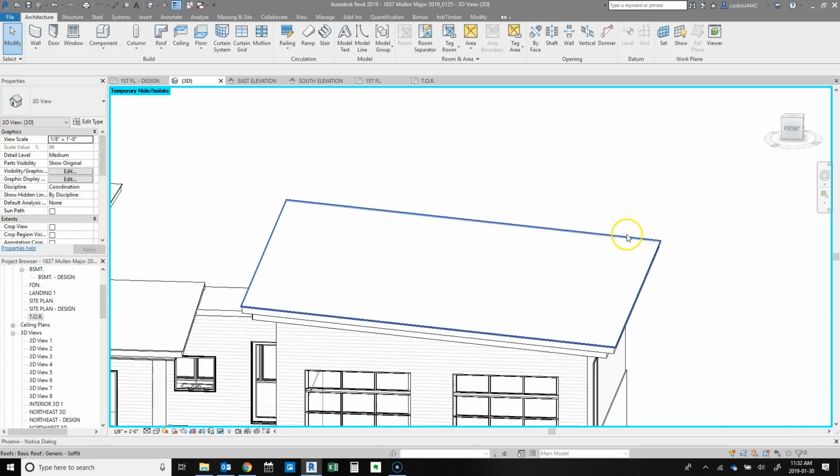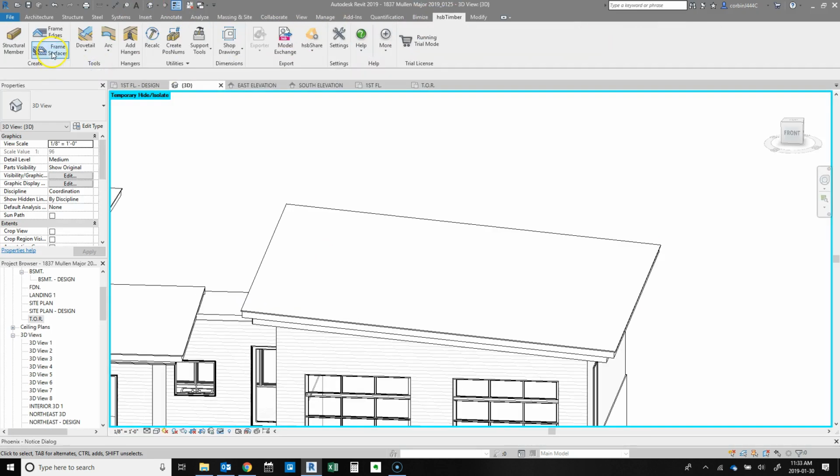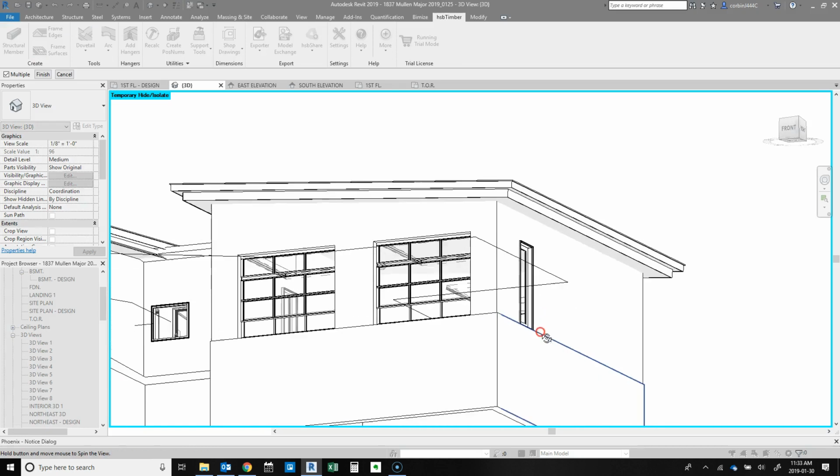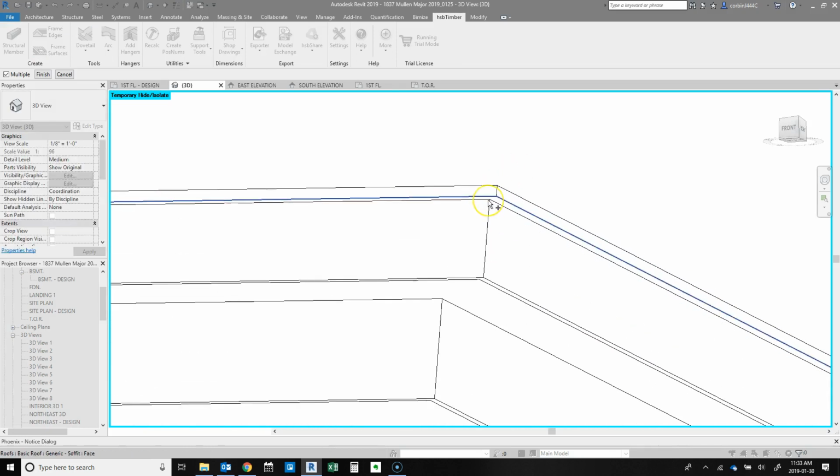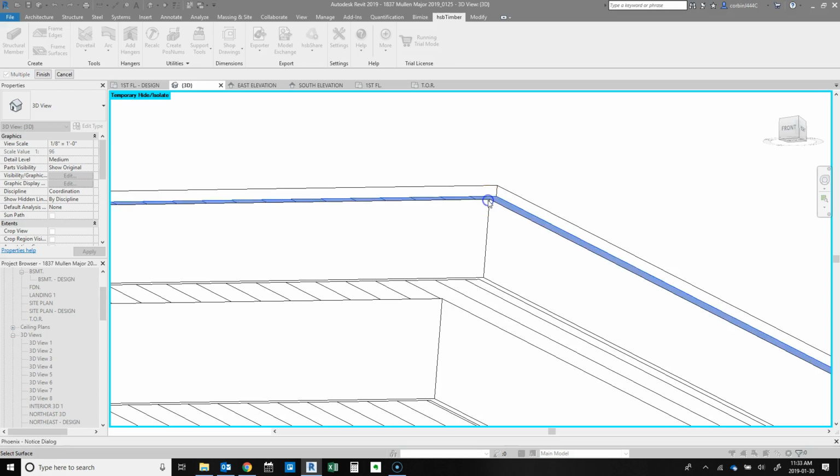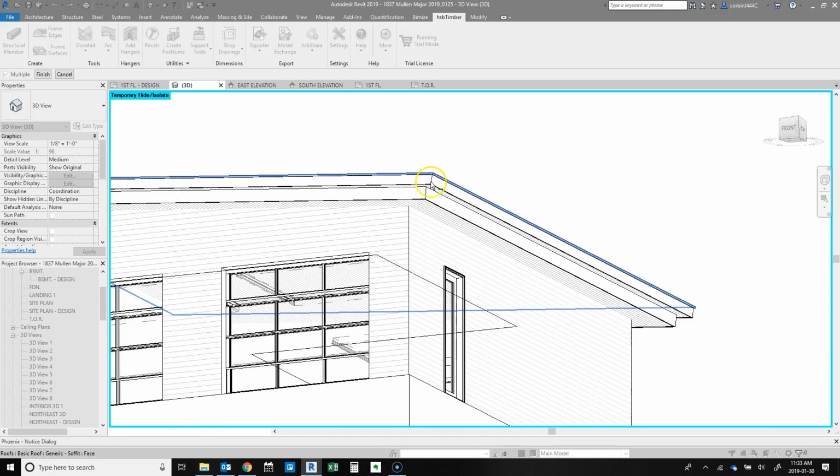And then the last step to this is we want to create our floor system. I use this plugin called HSB Timber. It just makes it really easy to create a grid. And with this, all you do is select the bottom of the roof plane surface. So you can see how that goes there, and then we just click the finish button here.